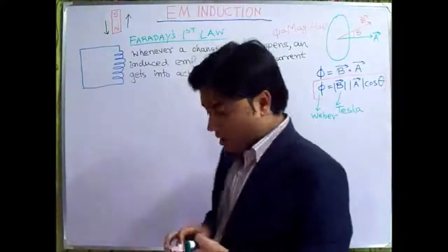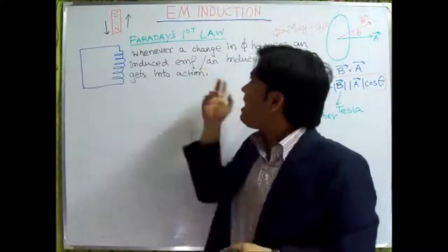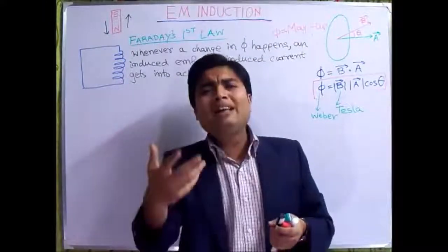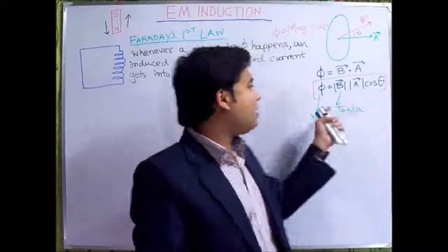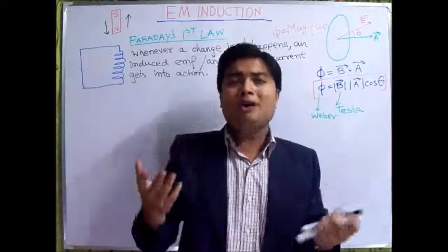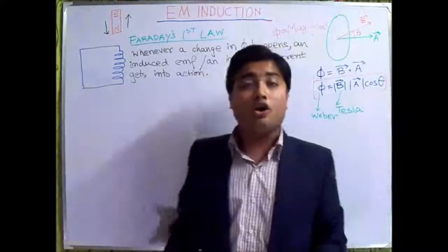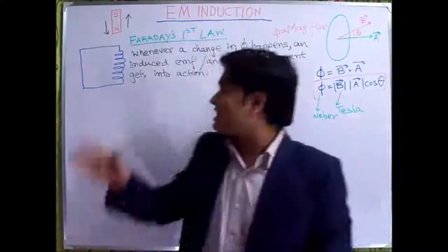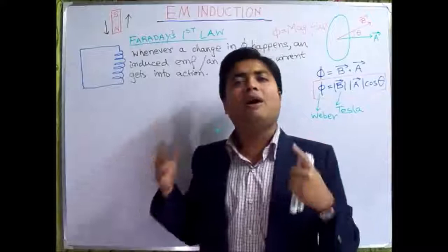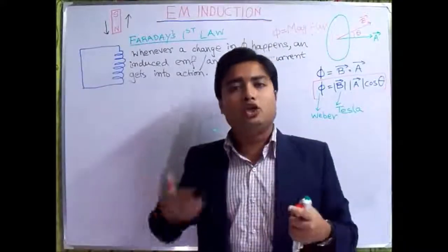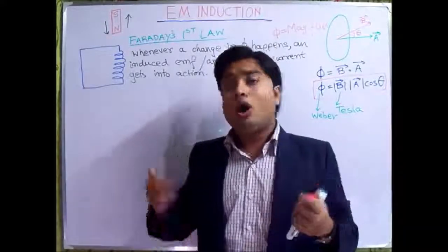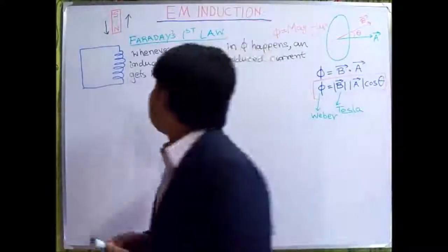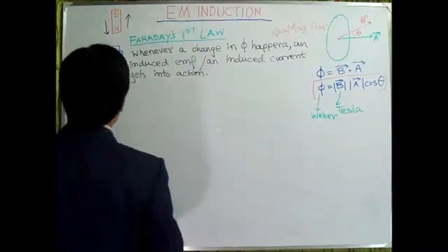But from Faraday's first law, you may ask: for how much change of this phi, or magnetic flux, how much induced EMF will occur, or how much induced current shall occur? Because this does not tell us anything about the magnitude of the induced EMF or the magnitude of the induced current. Now that could be answered by Faraday's second law.